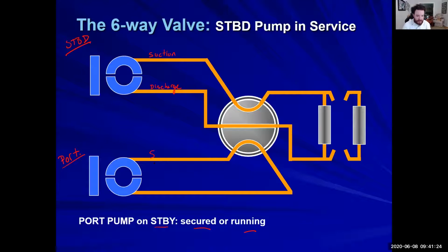Same thing here, suction and discharge. If this port pump is secured, we're going to have nothing flowing anyway. It's off. Doesn't matter. But in some cases of vessels, you will see the standby pump running. It's just going to be sucking in fluid this way and discharging fluid this way. And it's going to be going into this six-way valve, comes back out of the six-way valve, and goes back into the pump. That's all it's going to be doing the entire time it runs because it's in the standby position.